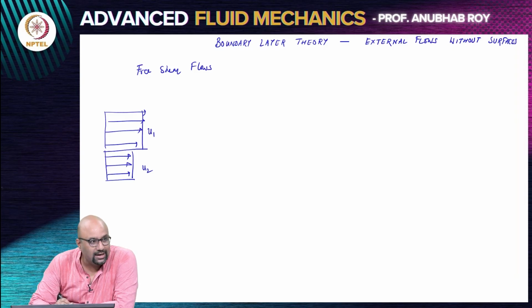And we did the unsteady calculation, and we said that gradually the transition region for going from the velocity in the top layer to the bottom layer basically grows as square root nu t. So, we also thought of it as a diffusion of a vortex sheet. So, it is in some sense related to the first problem, that of an impulsively pulled plate. Now, if you think of this problem instead of an evolution in time, you can think of it as an evolution in space.